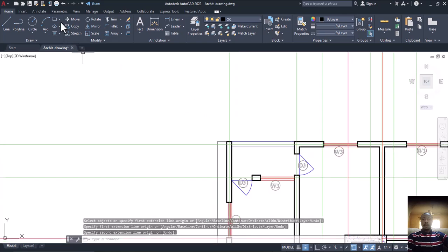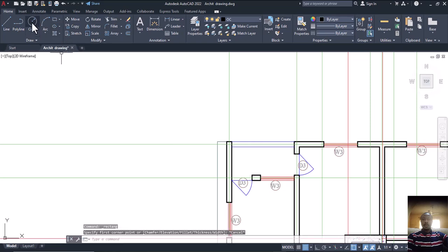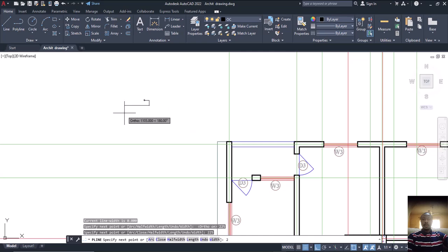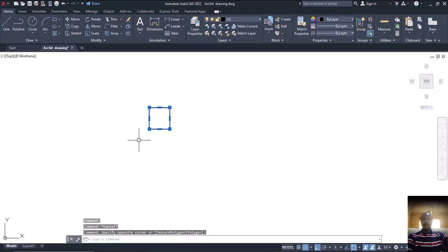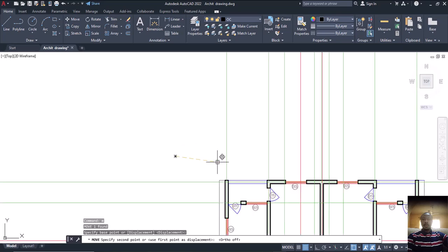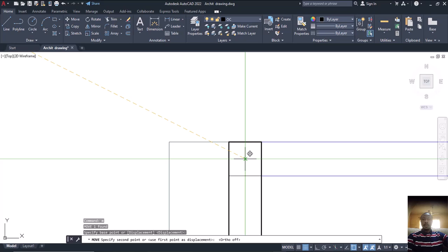All right. So I'll come here now. Let me use my polyline. I'll come here. Let me put my straight, then 225, enter. Then 225, enter, and come here, 225. Enter and finally I close it up here. If I click on it, it's showing me. Is that okay? I'll select this one now. Enter. From the point here, I will move straight to the intersection point, which is at this place now. I'll click on it.